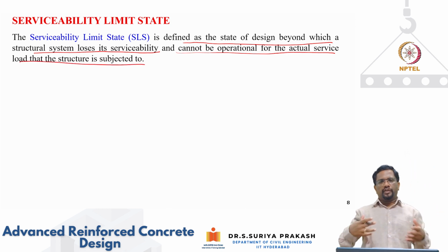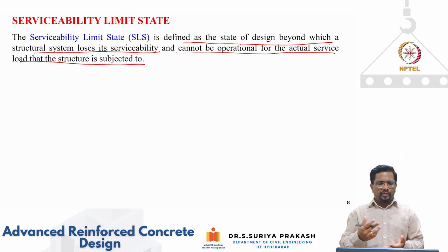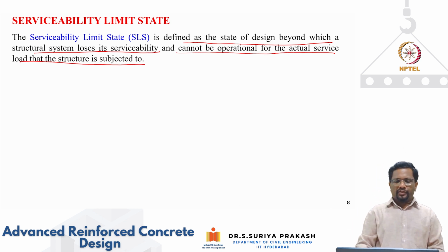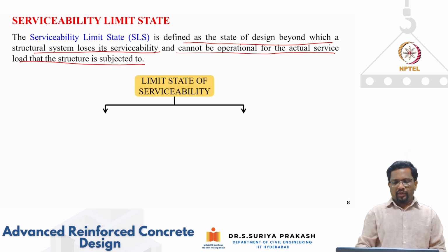If you have huge deflection, then while you're walking on the slab, you may feel uncomfortable, right? Similarly, when you put equipment and the floor is deflected, then the equipment may not be able to function properly, right? So these are all operational issues. So the system is going to lose its serviceability and it will become inoperational, right?